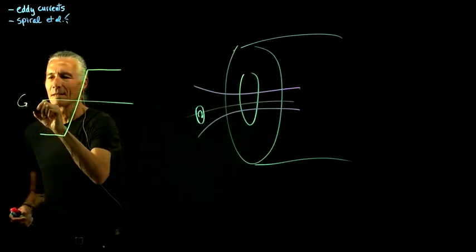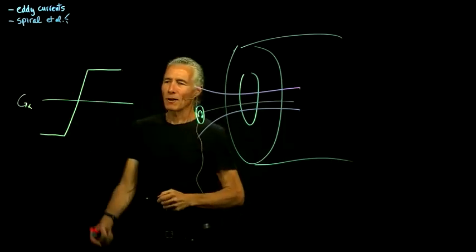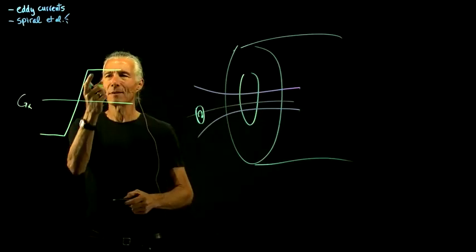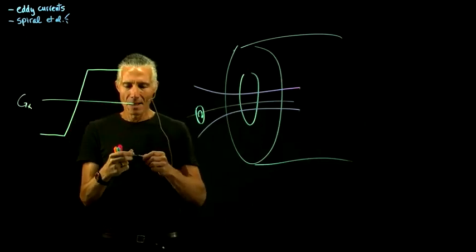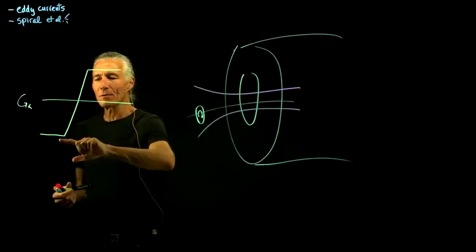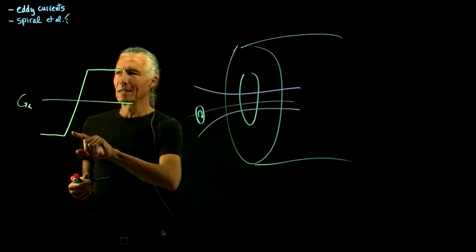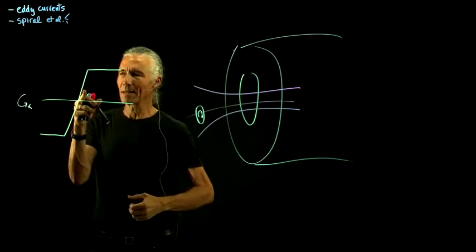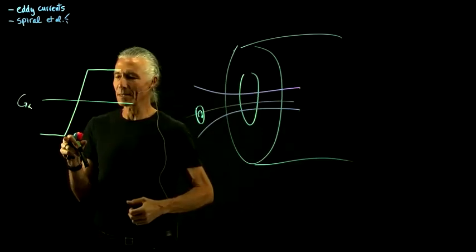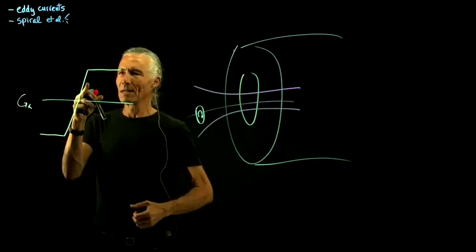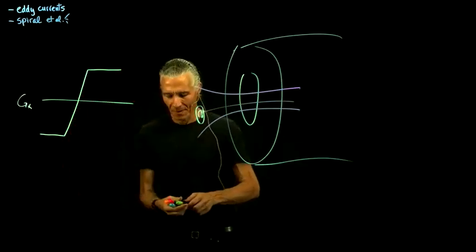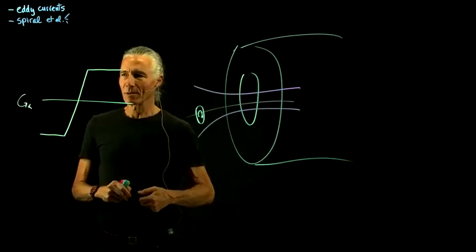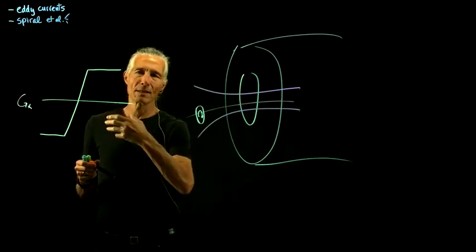Say this is the X gradient, and I draw a pulse sequence where first we go to the negative side of X K-space, and then we go to the positive side. If you tell the gradient coils to do this, putting negative current in one direction, then ramping to 0, and then going to positive current, what will actually happen if you measure the magnetic field that came out of the gradient coil? You can put a sensor in there and figure out what the gradient coils actually did.